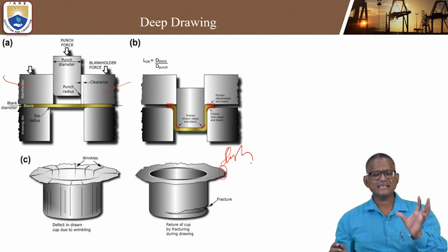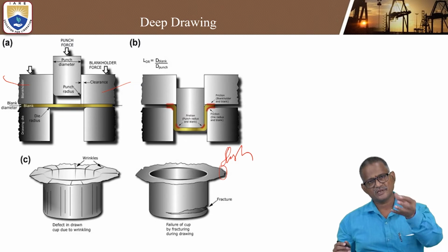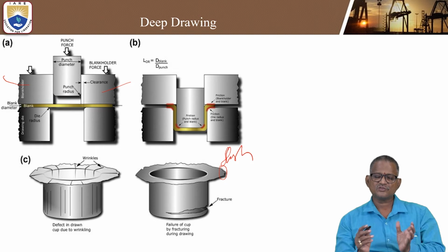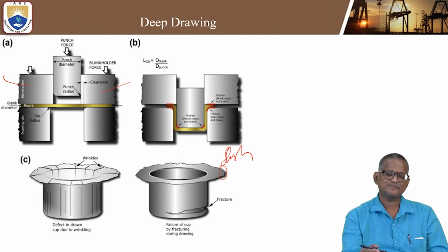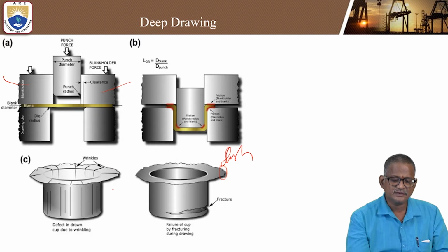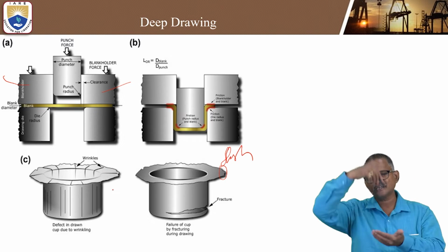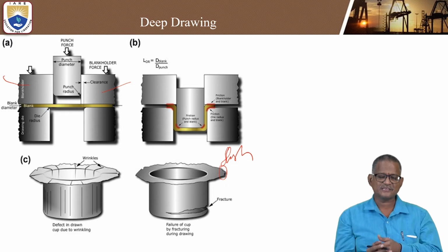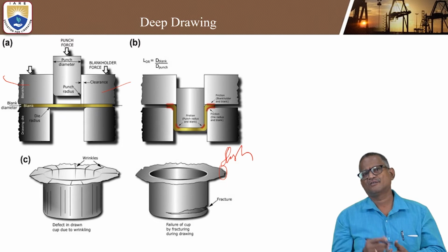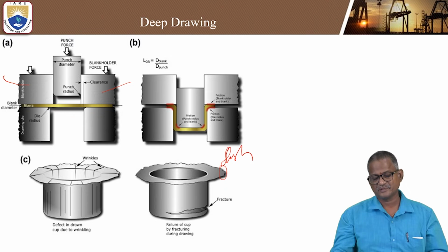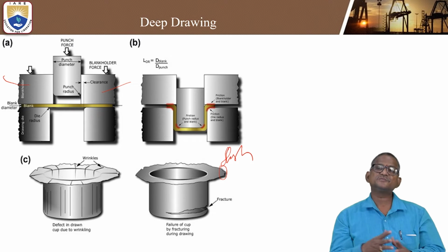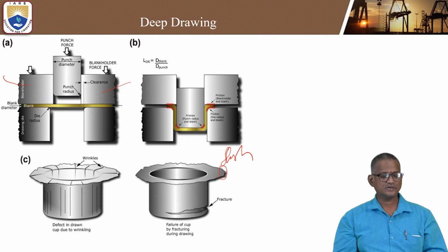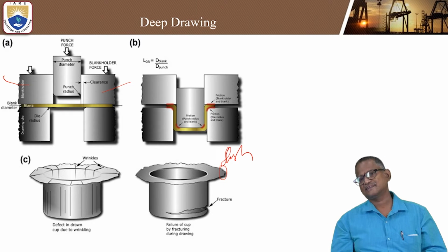What is the exact amount of material to be kept there? So it is open die forging, like that. If it is closed, this type of flash cannot occur. Okay, these are some wrinkle shapes. Suddenly if you apply pressure, some metal may wrinkle together depending on the pressure in that process, so that leads to a defect. Again, I have to remove that. You can use some machining operations like grinding, etc.